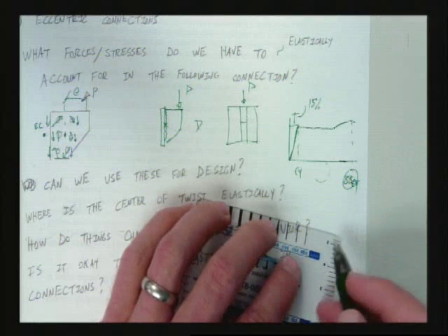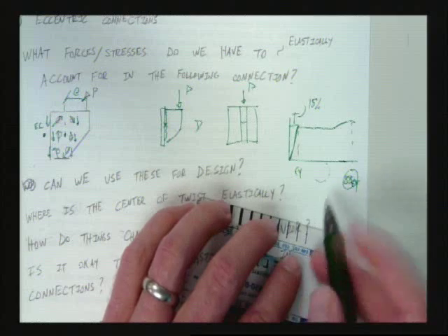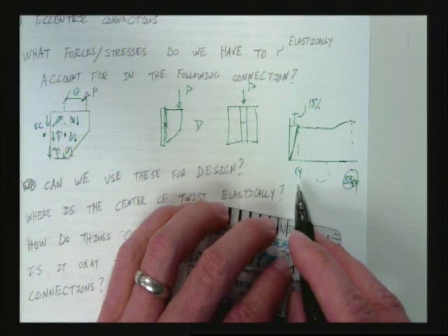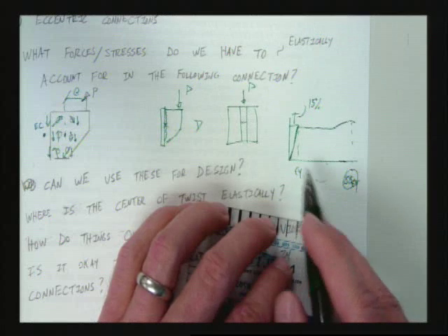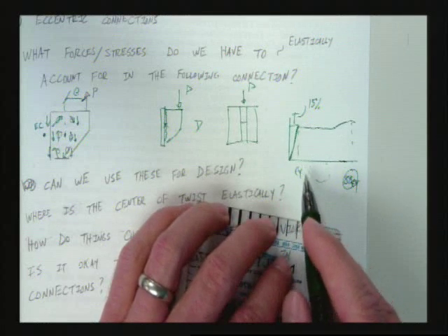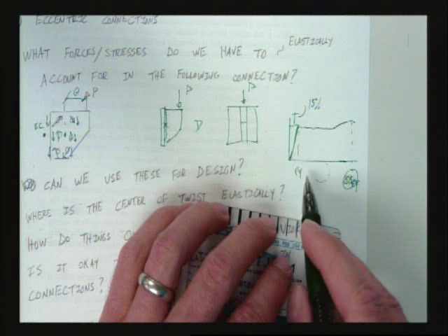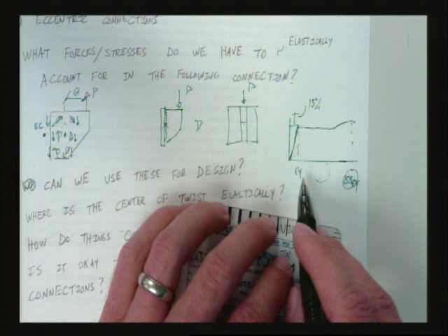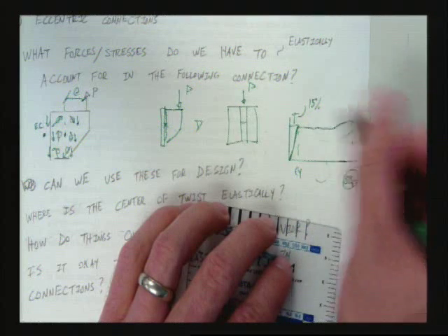That's why limiting yourself to only one bolt being engaged, or limiting yourself to when yield just very starts to happen, is highly cautious. Because look at all this play we got in here.